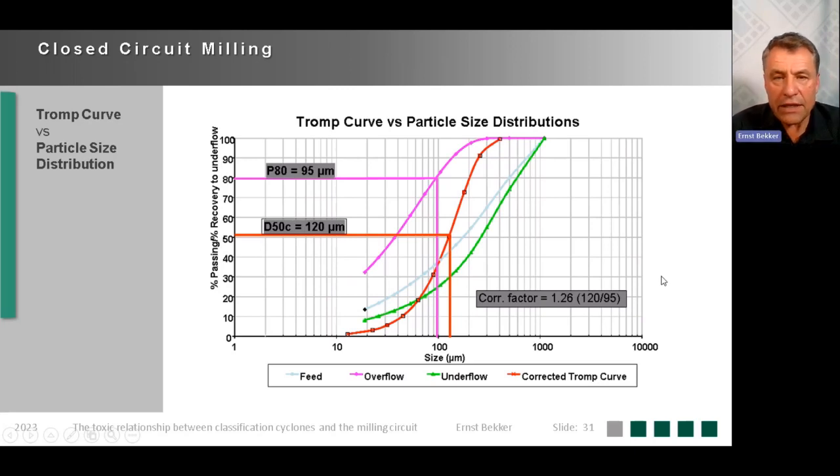So that is how we select milling cyclones. Obviously, there's the throughput, the number of cyclones, but the point to be made here is there's a relationship between the cut point of the cyclone and the overflow. Often people would ask, why is my cut point coarser than my grind? And unless you understand these set of graphs, it's very difficult then to explain to the client.